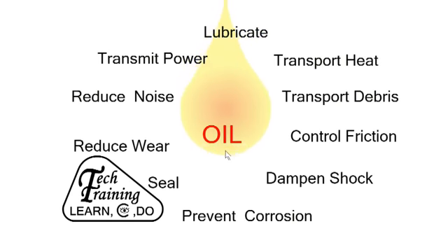As manufacturers strive to improve efficiency and economy, it places a more onerous task on the lubricating system. Engines run at higher temperatures utilizing the minimum amount of lubrication oil. The characteristics of the oil are improved with additives which inhibit corrosion, reduce foaming, reduce oxidation, and act as a detergent.